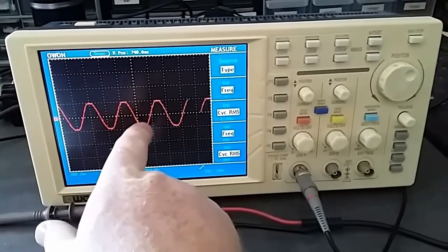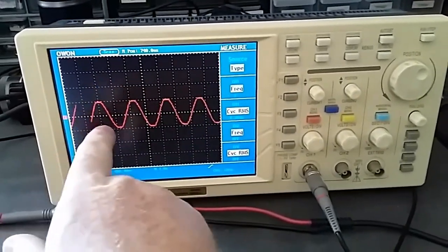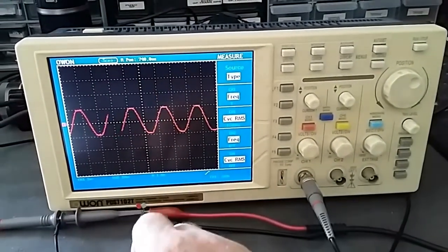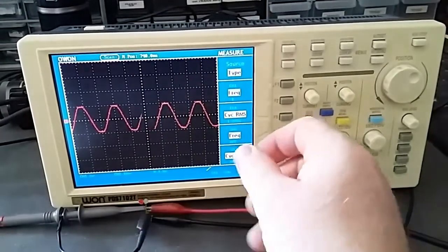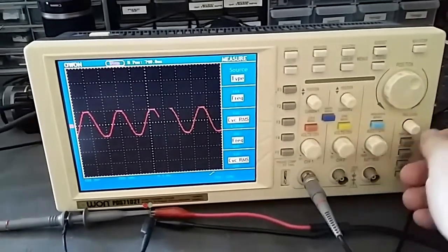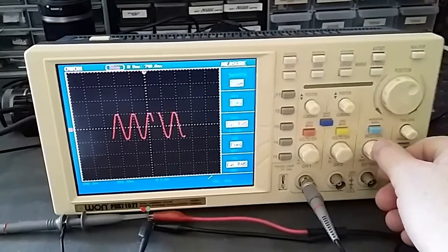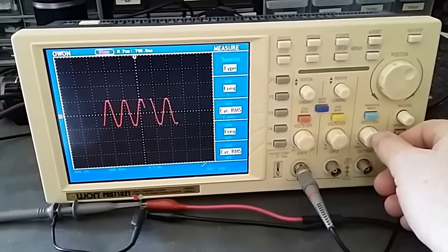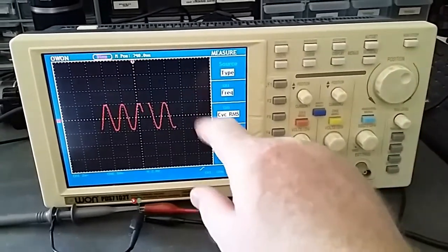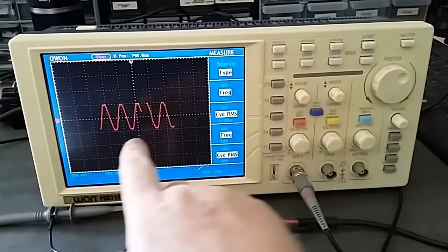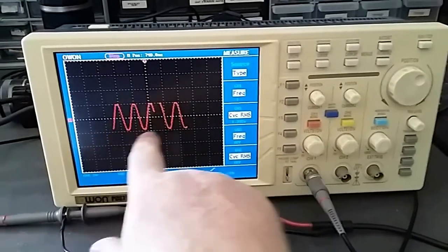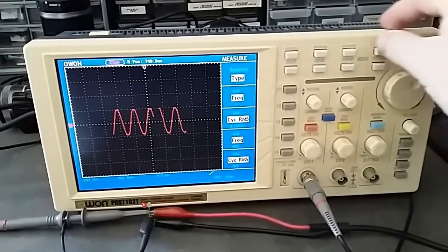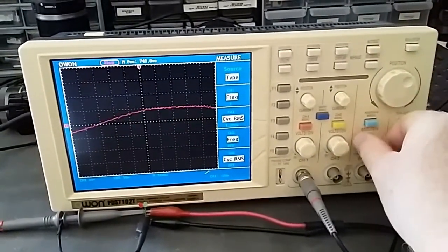Okay, so what's written on the screen at this time, moving from right to left, all this data over here is old data that's been stored, and it's being overwritten as we go through. If we stop it, that chunk of data there is what's being stored in the buffer, in the memory of the digital storage oscilloscope. This is what's being stored, and you can see that in real time. You can zoom in, zoom out, all that sort of thing.